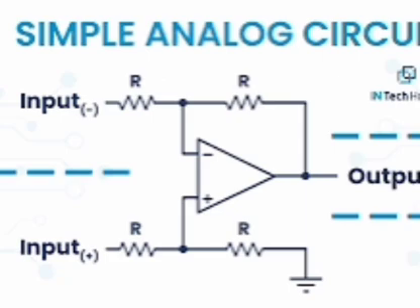Remaining parameters are same as full wave center tap rectifier. Remember, type of transformer: half wave rectifier, normal step down. Center tap based full wave rectifier, center tapped. Bridge circuit based full wave rectifier, normal step down.